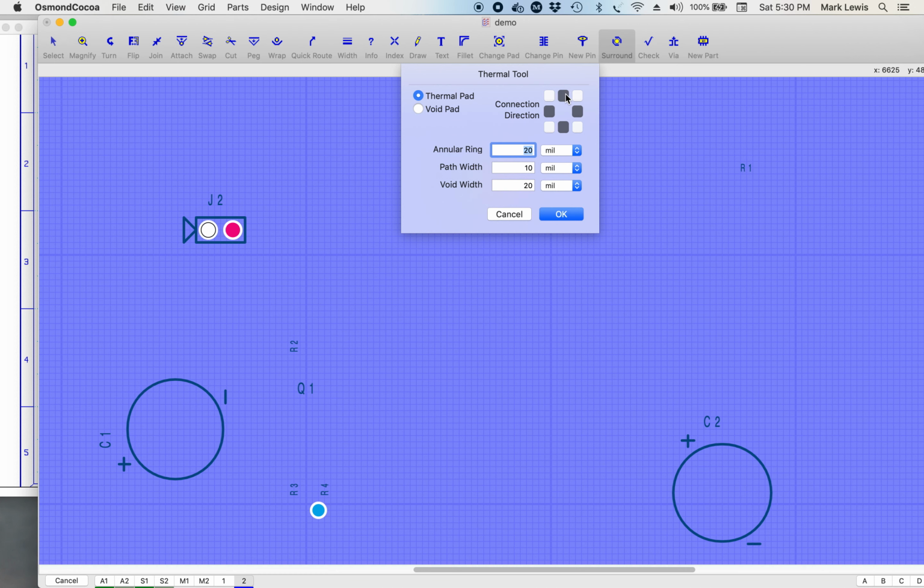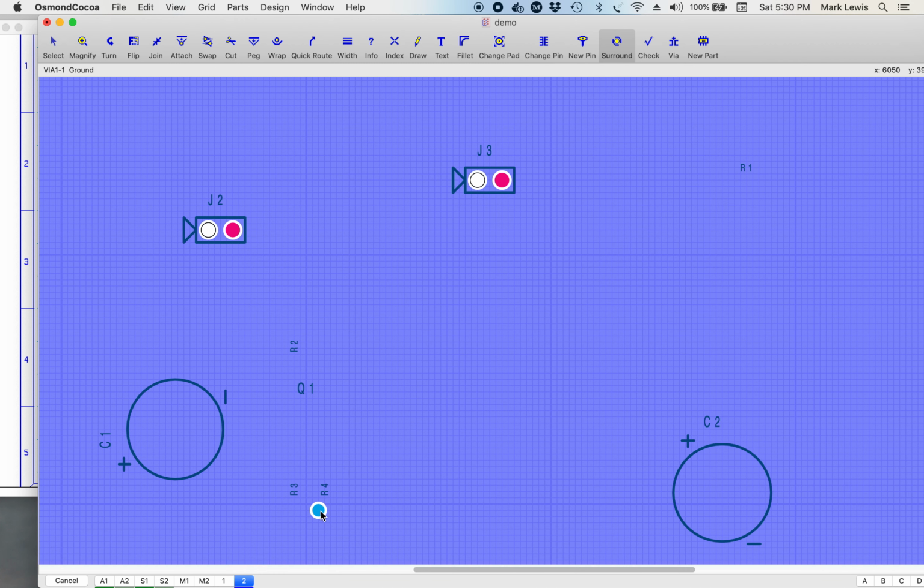I usually like to have a really good ground when I do things, unless I have a wire passing across one side or something, then I might unselect one of these, or I could select all of them if I want. Let me show you the difference. If I just do it like that, 4 parts of this hole, this via will be connected to this ground surface. We'll click on it, and you'll see the 4, 1, 2, 3, 4.